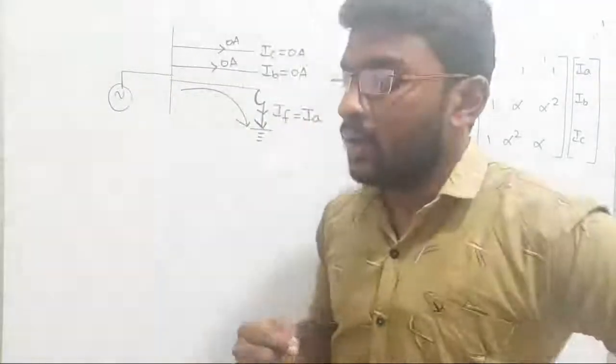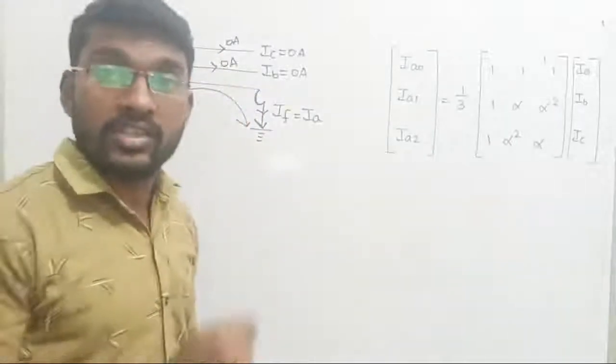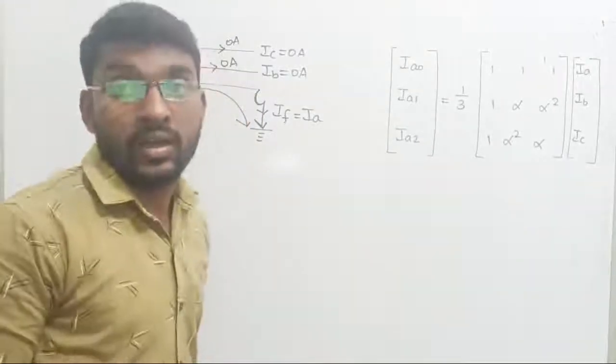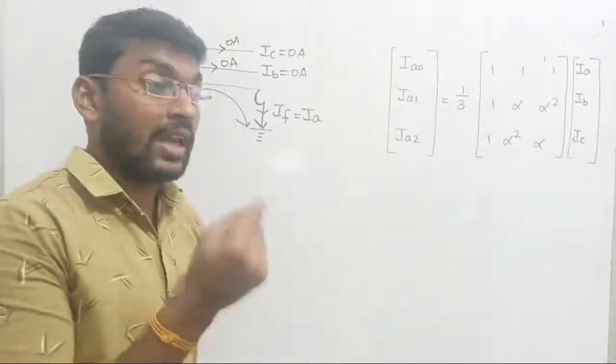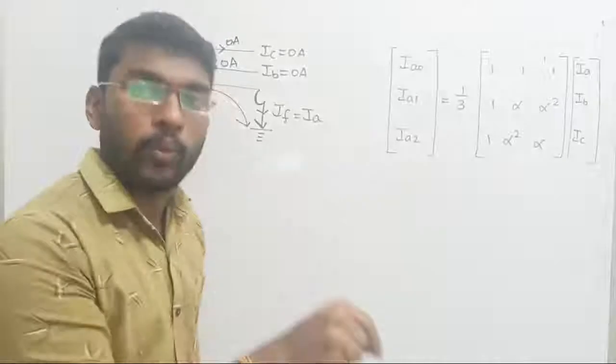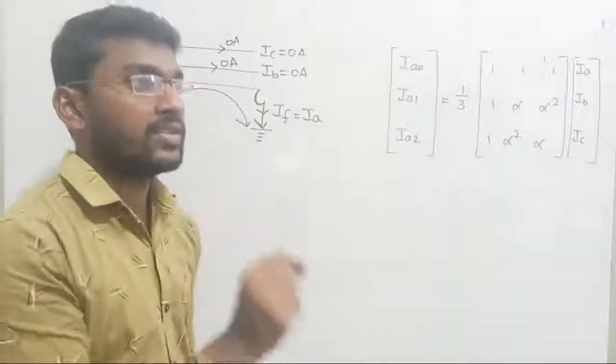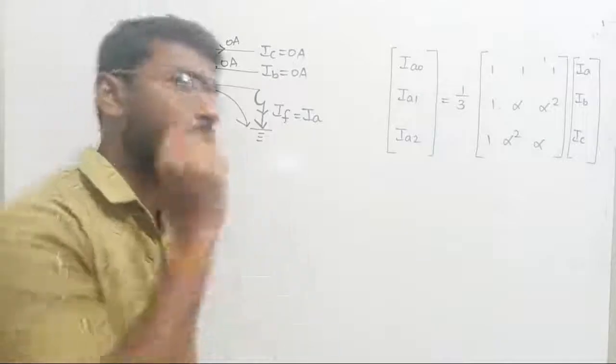Already we have seen in the case of star connected or delta connected networks, it does not matter which type of three phase connection we are using, whether the line is closed, whether the line is attached with the ground or not. If there is no point of discussing about the ground point, if there is no ground line, then there is no point of discussing the zero sequence component, which is going to be 0.